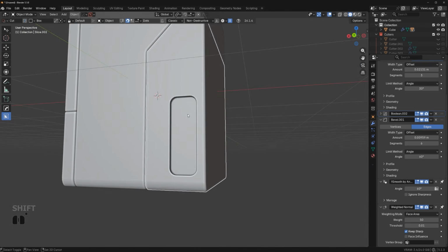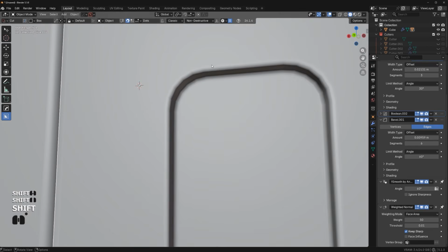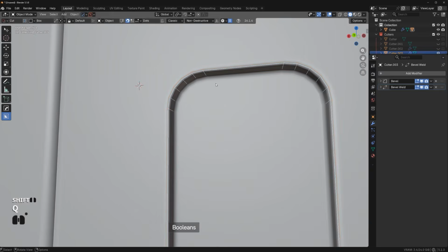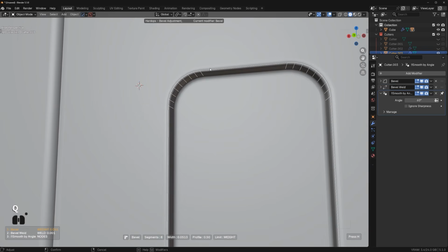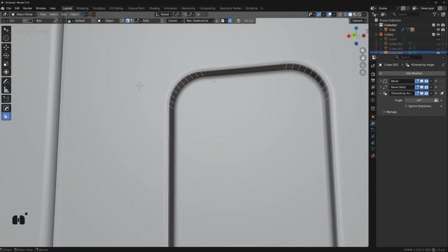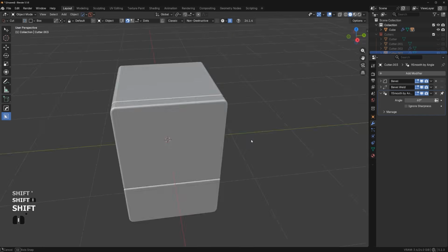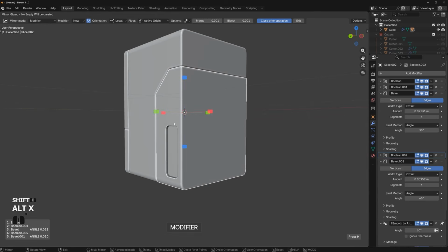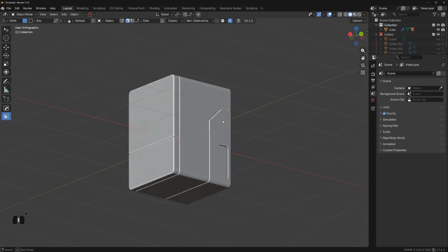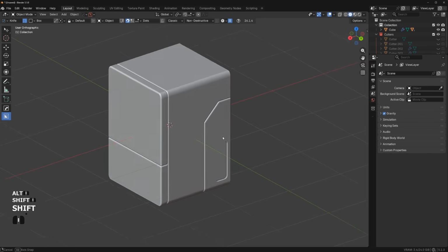Okay, otherwise it will not work. Now this cutter could have higher resolution, so let's go to F scroll, go to Q menu on the cutter, bevel, and scroll up to maybe, I would say, 9 segments, and Shift 2. That will do. Cool. And we can actually keep this symmetrical, so we could just mirror this to the other side. Well, we're going to leave it for now, and we can put a decal over there later.